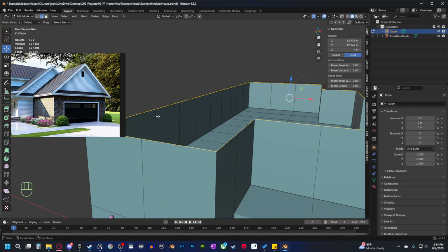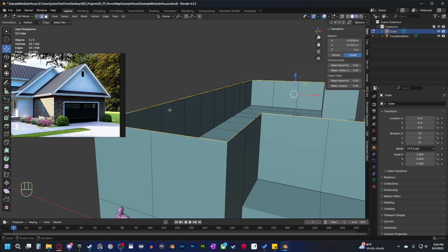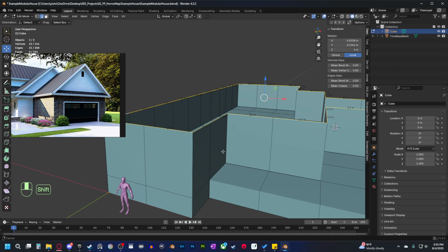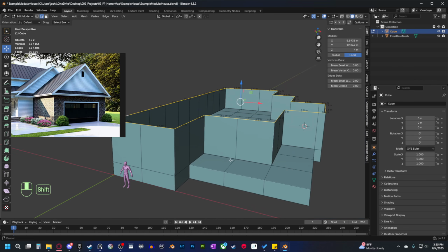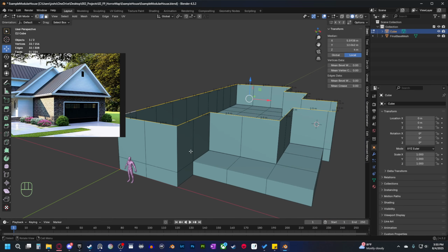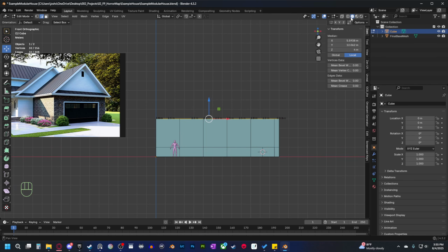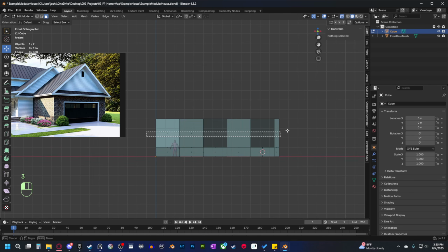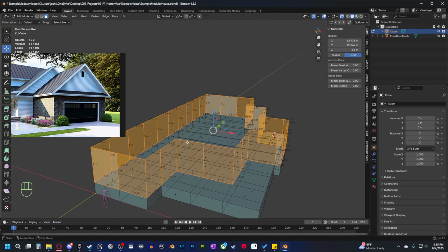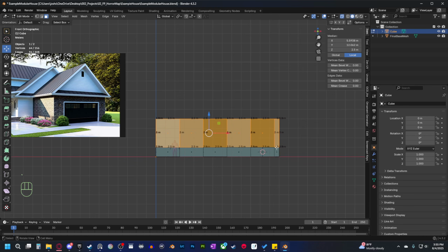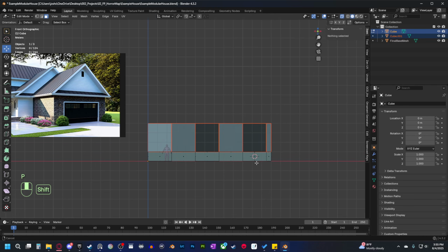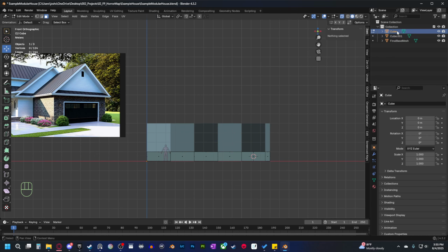And then you can always, of course, have slightly taller walls and bring in your ceiling and make it whatever size you want. So yeah, I think that works well. Now, what I'm going to go ahead and do as well is select basically our first floor walls. I'm going to hit P by selection, and now I'm going to call that, we'll call it first floor shell.